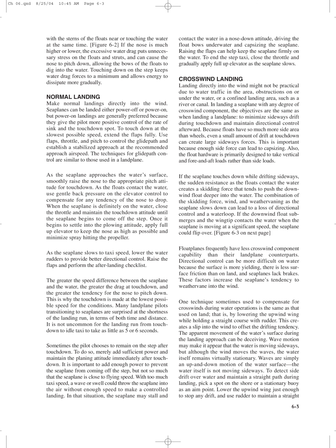Floatplanes frequently have less crosswind component capability than their landplane counterparts. Directional control can be more difficult on water because the surface is more yielding, there is less surface friction than on land, and seaplanes lack brakes.